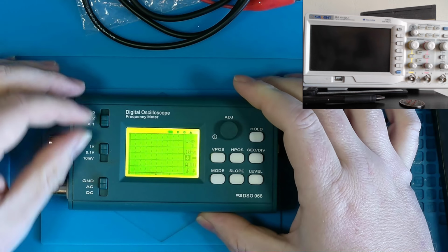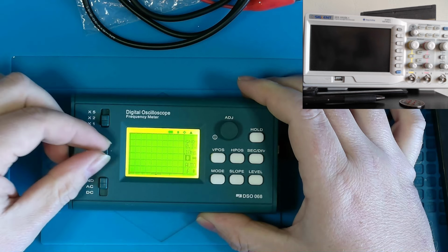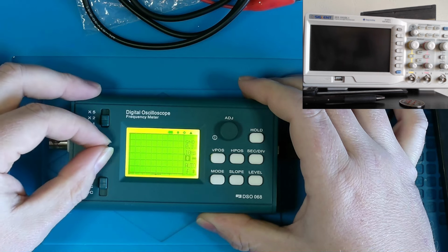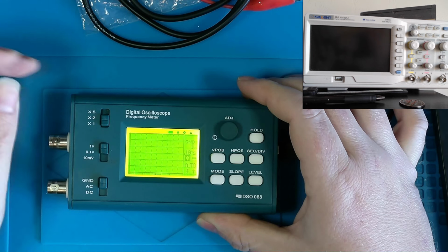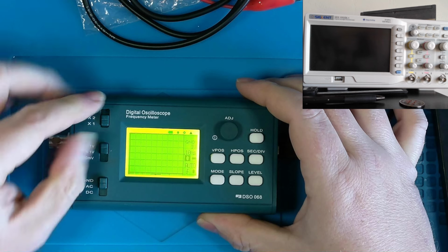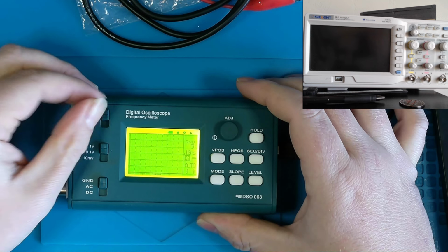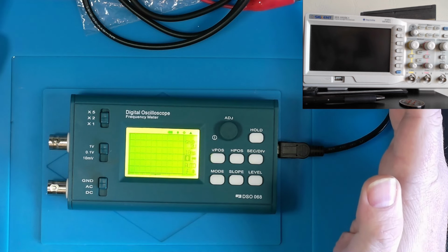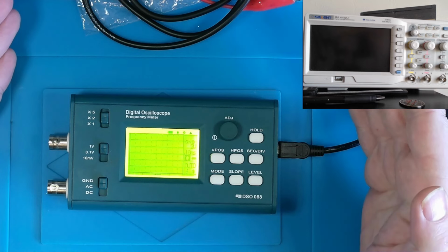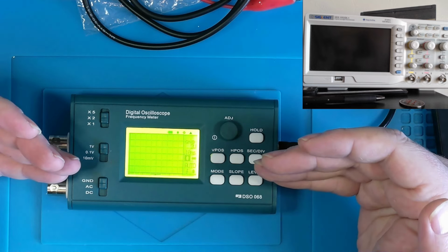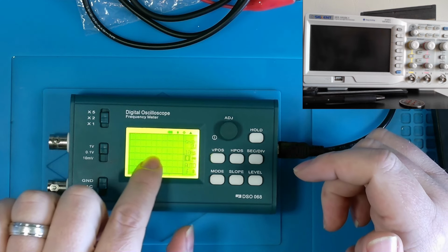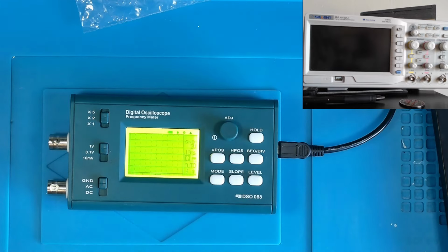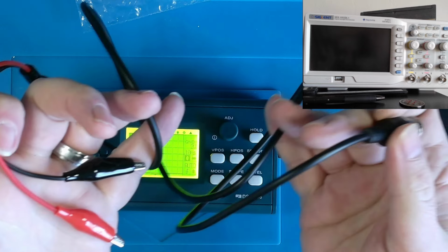Now I've also realized not just do we have voltage selecting here, 10 millivolts, 100 millivolts, 1 volt. This is a multiplier, so we can go from 1 volt to 2 volts up to 5 volts. Now, I'll leave it on 2 for now. So what I want to do is we're first going to use this to make a DC measurement. Now again, my reference is set on the center. I have this set to ground. And for this type of measurement, I'm going to use this probe right here.